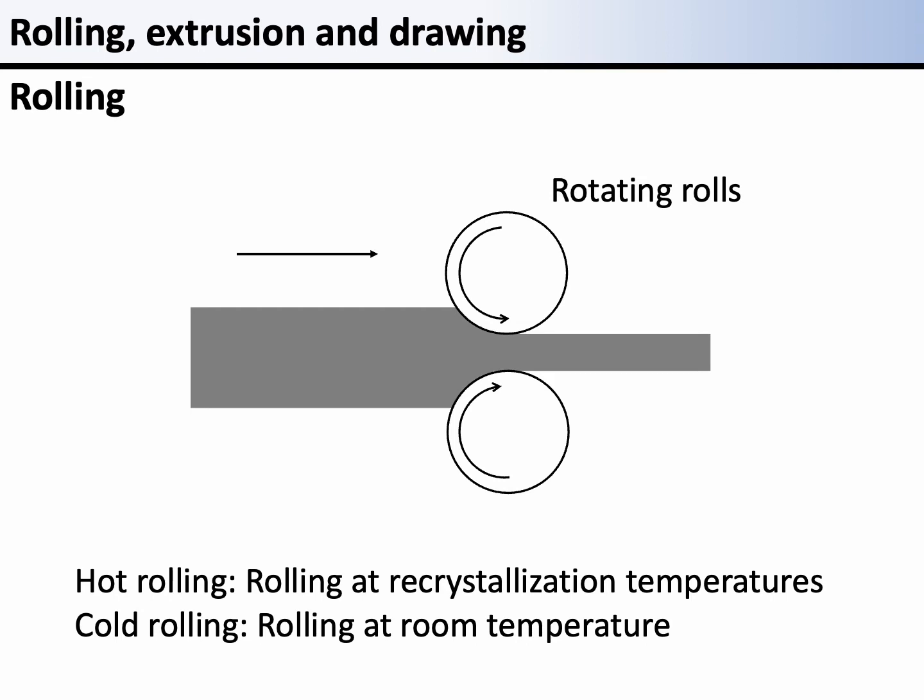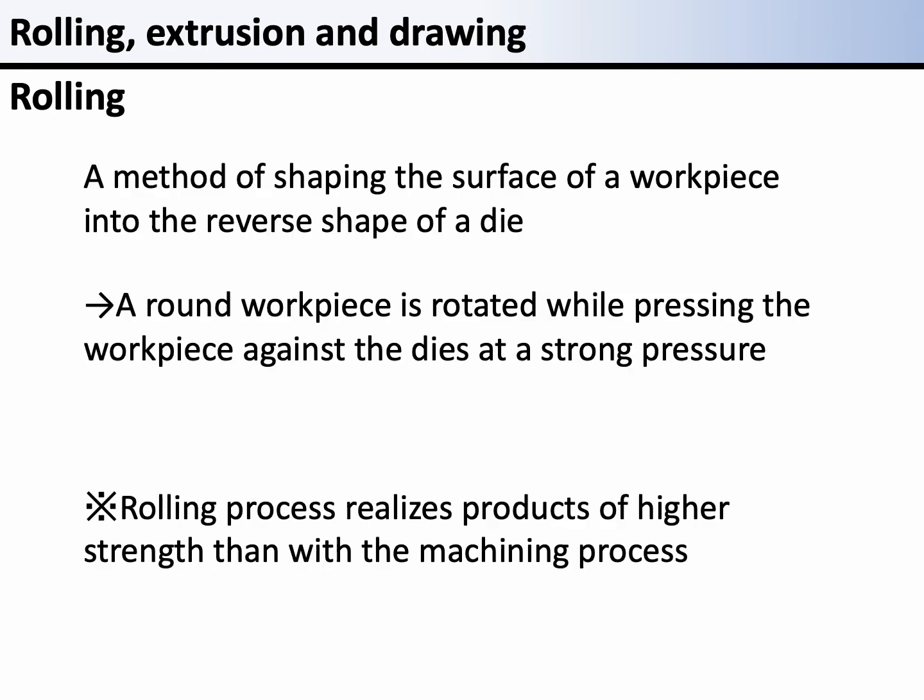Commercially available steel plates and other shapes such as H-shaped steel, I-shaped steel, and others are formed by hot rolling. The cold rolling process is used to further reduce the thickness of a hot rolled plate. Generally, steels covered with a black membrane are the products shipped from hot rolling.